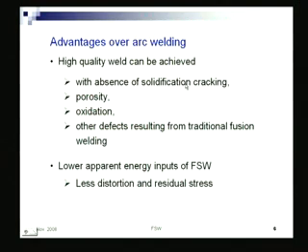So, if there is no melting, the possibility of such cracking will not be there. Similarly, no porosity, right. Porosity is caused by gas entrapment. No oxidation, because here there is no necessity of shielding, because the temperature rise is such that not much additional oxidation is taking place.